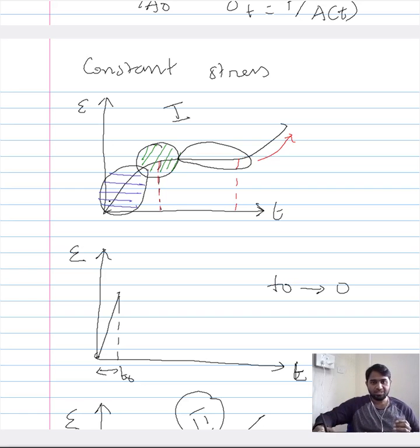One is the instantaneous elongation of the material. The other, let me use this color, is where the strain is almost constant. You have two characteristic regions in the creep curve, and between these two you have a small region that connects them, during which the slope of the creep curve is gradually decreasing.